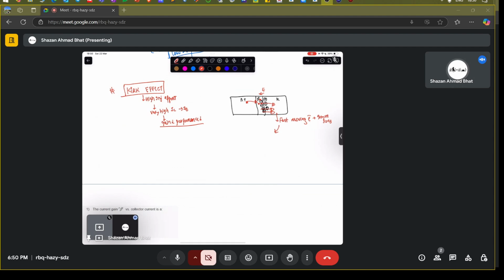When you draw the band diagram and other things, you need to solve something called the Poisson equation. Let me write the Poisson equation in 1D, which looks something like this. This is the Poisson equation, where this term is the mobile electrons and this is the immobile charges, which are the immobile ions.